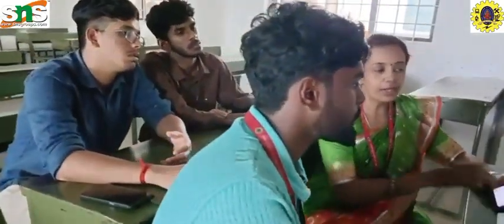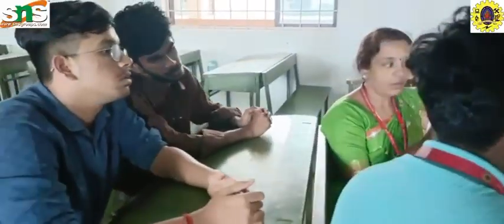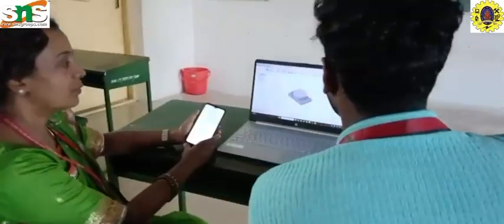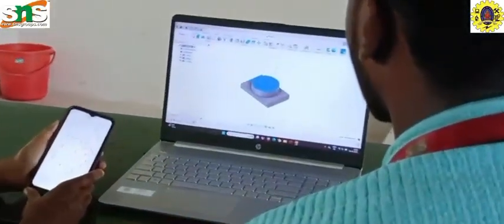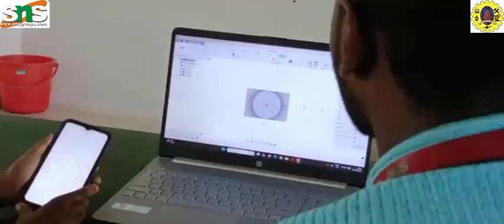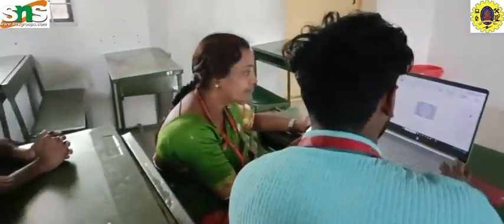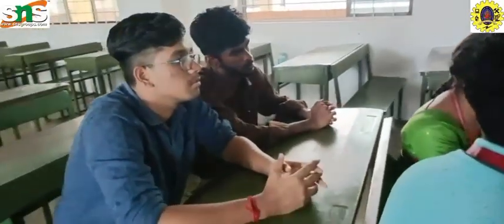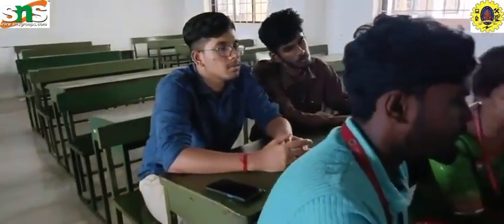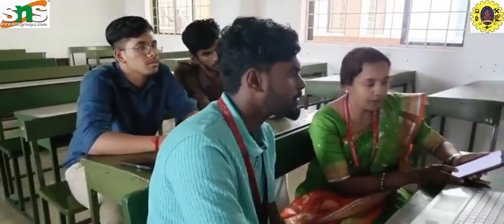Extrude, yes. Whenever you complete the diagram, you have to click finish sketch. Only then can you convert the 2D into 3D easily. Okay, so we have got the part model. One more circle we can draw, of dimension 60. Then we move to finish the sketch. Even in the extrude option itself, if we want to cut, we can use the cut option.